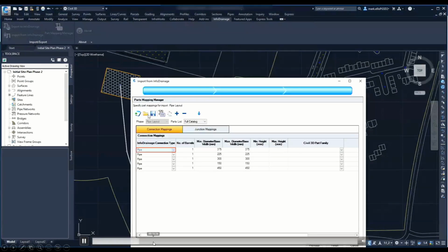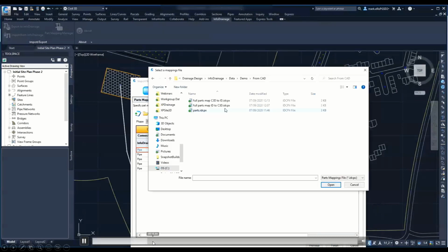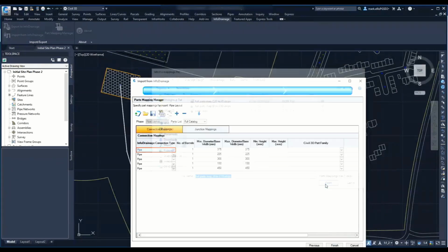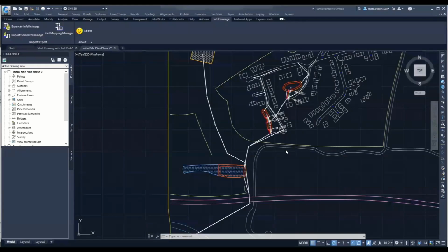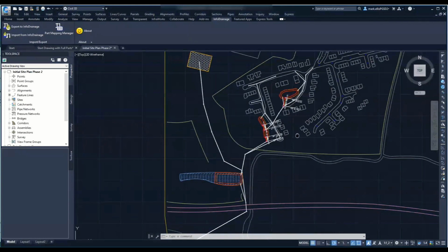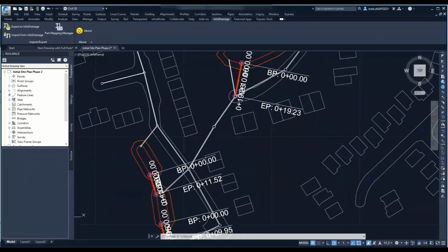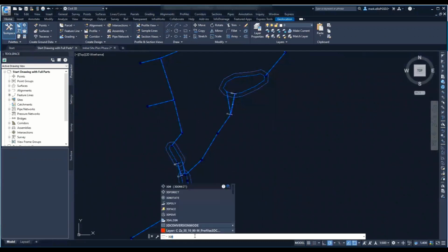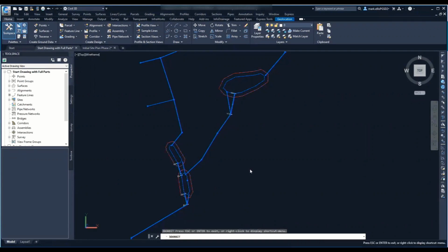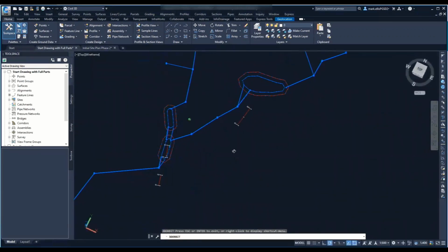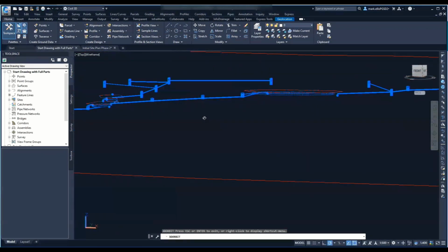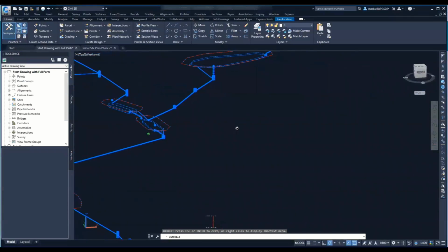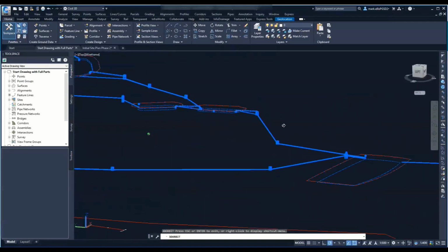So in this example, actually bringing in a model that contains some swales and a biobasin. You'll be able to see the visual representation of the design in a couple of the native Civil 3D views, including the useful 3D orbit. So our stormwater controls are accurately represented in the surface as laid out on plan in InfoDrainage. So further design iterations within Civil 3D are minimized by maintaining correct connection. Inlet and outlet locations are in the correct locations as well.